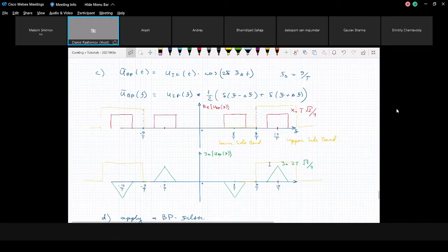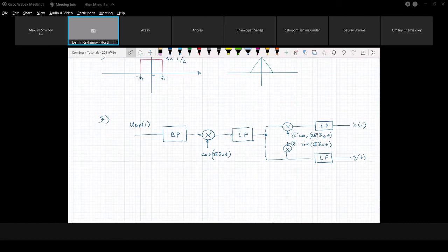And the first bandpass filter selects the band that you want to work with, upper or lower band. For this reason, you need two filters, even 3 filters, because after you select real or imaginary parts, again, you need to remove components with higher frequencies. For this reason, you need 3, even 4 filters. Yeah, no problem. If there are any questions, please let me know.